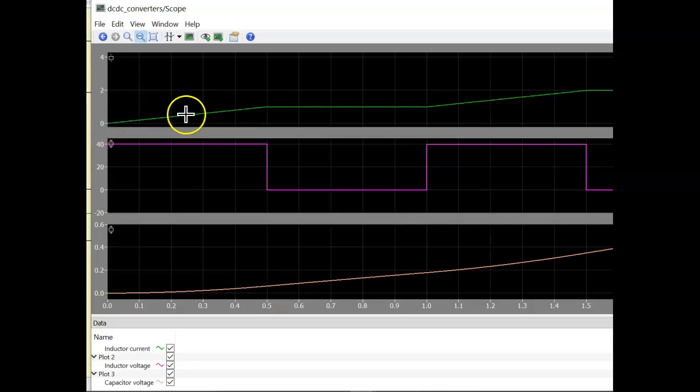So the inductor current rises to some value, and then in the next cycle the output voltage is again close to 0. It has not risen so much because the capacitor is starting to charge. So the inductor voltage is almost 0, otherwise it should have been minus VO. Since the inductor voltage is 0, its current doesn't appreciably rise,